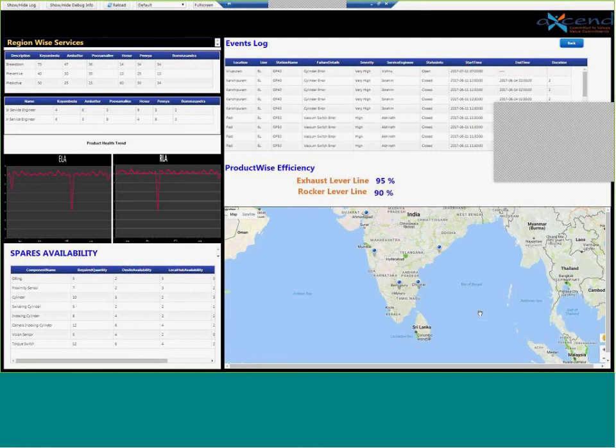Do you take into account the environment that the machine is running in? For example, a NEMA 1 rated machine versus a NEMA 4X. Is it in a harsh environment, a dusty environment, an explosion-related environment? Do you take any of that into account as well?